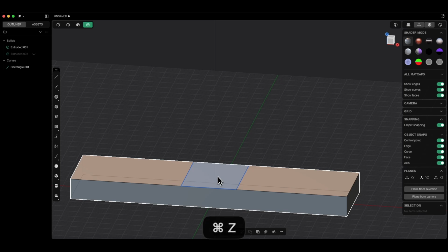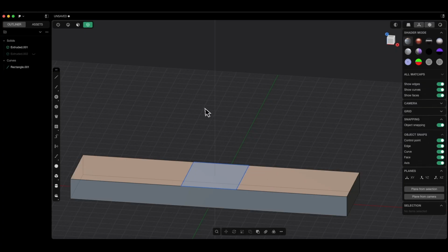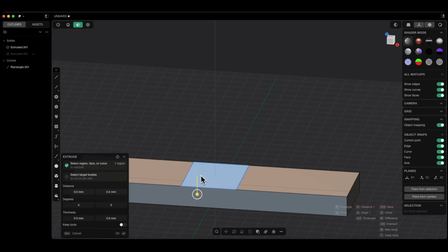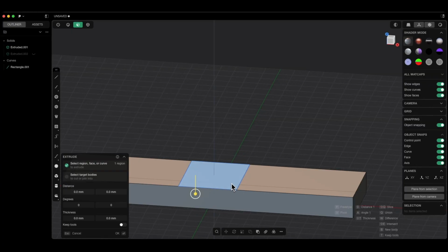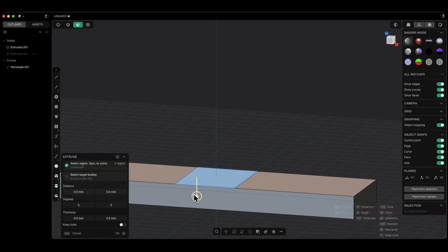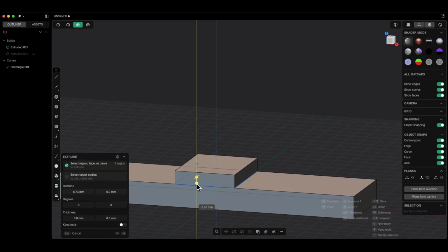And now if you want to create another section of the solid so that the extrusion we make from this geometry is automatically joined with the existing solid, we can do this during the extrusion operation. I switch to face selection mode and select the area of this rectangle. Here, as you can see, the gizmo is facing down. If you want to extrude upwards, in this case, we need to enter a negative value, but that's not a problem. I press D, type -15 and press Enter.